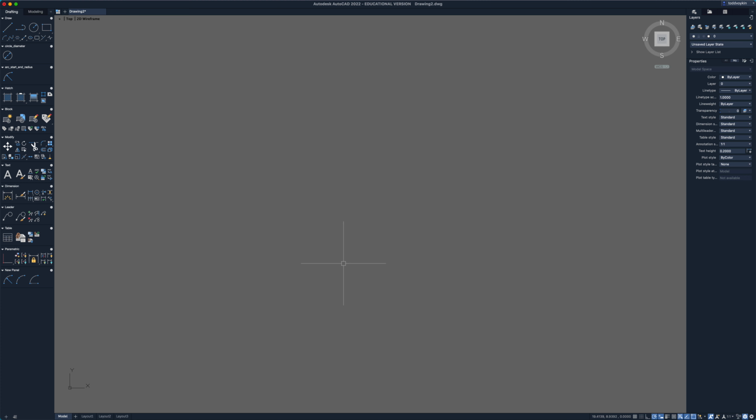What that does, if I'm making a line and I anchor it right here, you'll notice that I can sort of draw at any angle right here. But if I turn that one on, which again you can see is Command L, so if I'm just here and I go Command L, now I'm forced to only draw in a horizontal or a vertical direction.